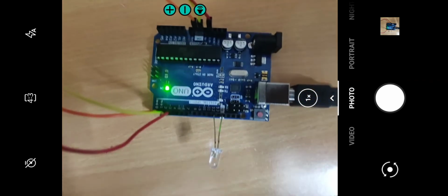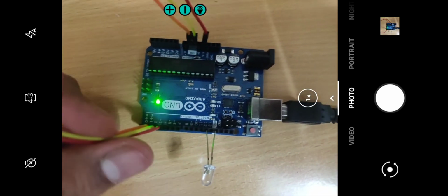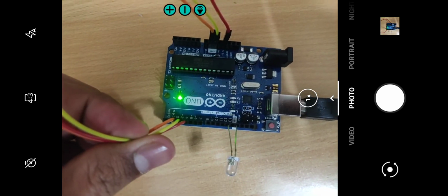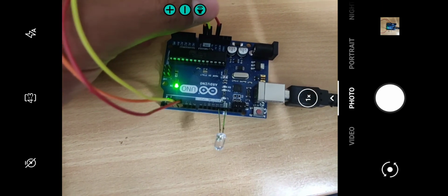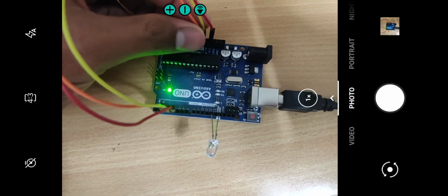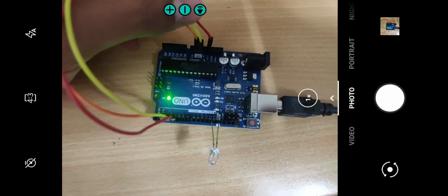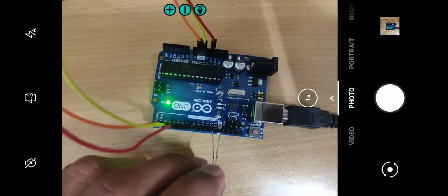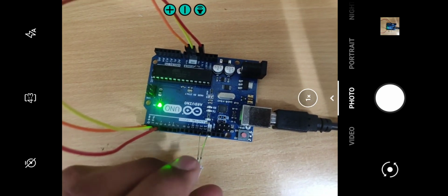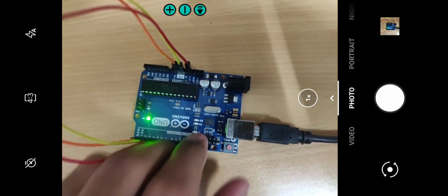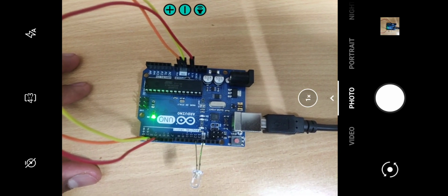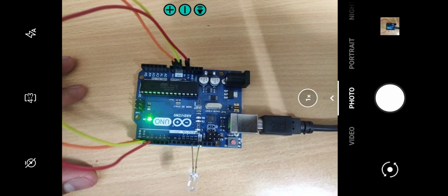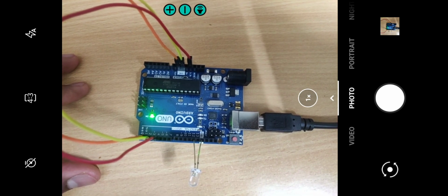So this is my hardware connection. Here we can observe 2, 3 and 4 are the GPIO inputs which I am giving by connecting them to ground or VCC. Ground and VCC terminals are available at the other side of the Arduino as pointed. And here we have external LED connected to pin 12 and internal LED, which is this one, connected to pin 13. So external LED represents the NAND output expression, while the internal inbuilt LED represents the minimized KMAP expression.